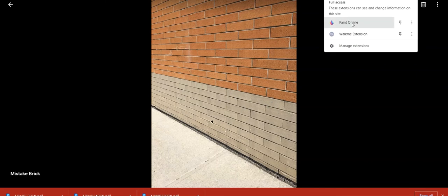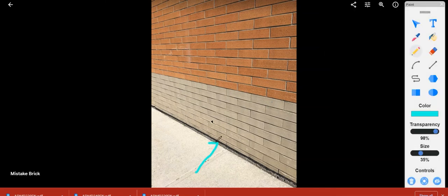Because what you don't want is stuff like this happening. Why on earth would you make a mason do that? If you work with the size of the product, so most standard modular brick is 57 high with a 10 millimeter mortar joint. If you work with that, work your way up, and design buildings so you don't end up with cut pieces like that. Less waste, less labor.